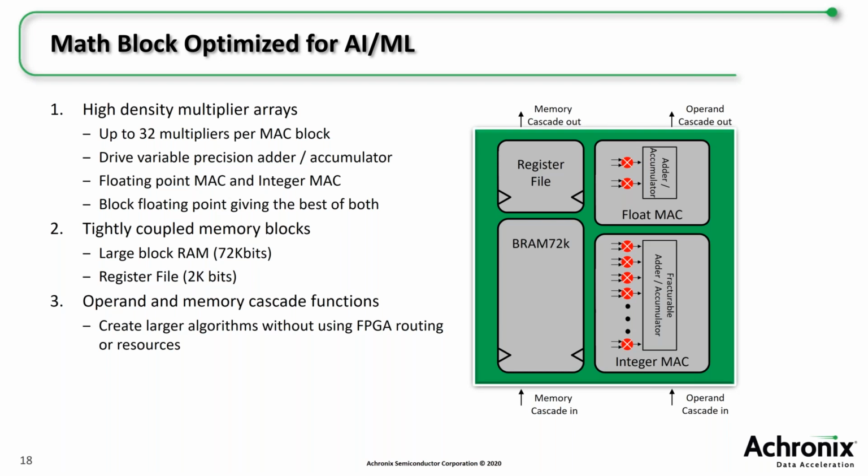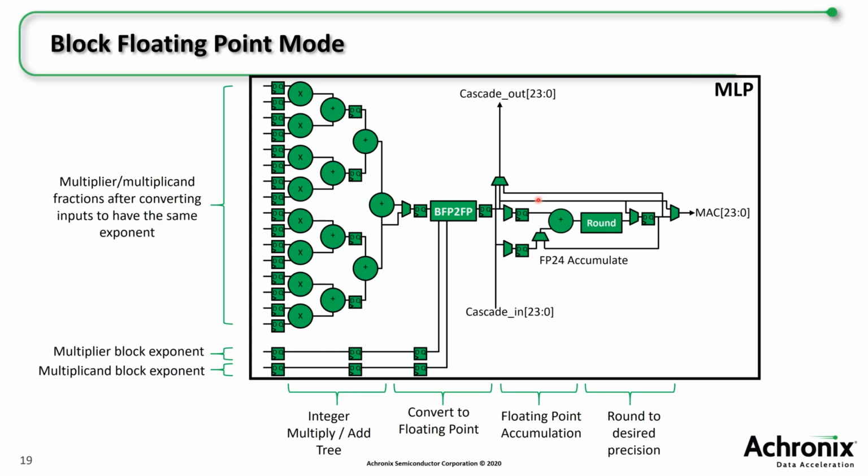Now, how this looks overall, specifically in the case of block floating point, I know this is kind of an eye chart, but if you look on the left-hand side, you've got a pretty simple fixed point adder tree over here. So you've got your two operands coming in each of the cases, and each of your values that you've got, where you've got 8 multiplications here that are being summed together, a second stage in the adder tree, and all of your 8 calculations are all being summed together. So this is a classic fixed point adder tree that we've got here.